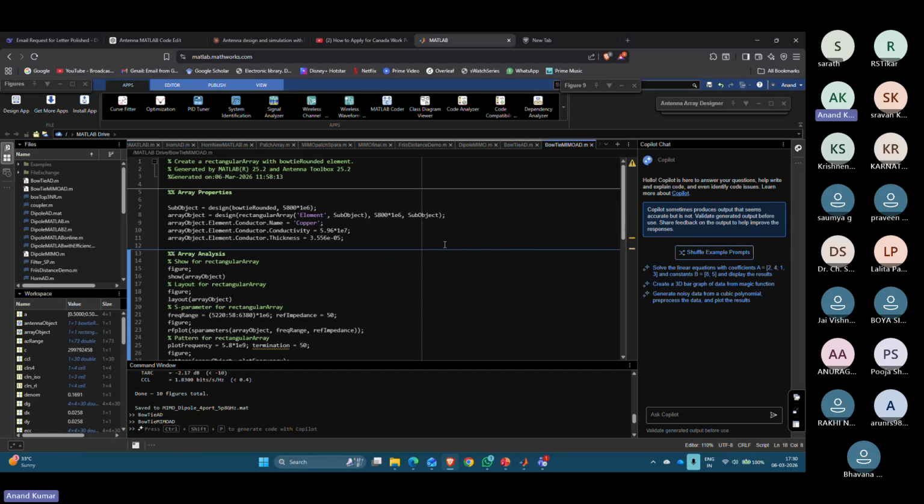It's just the one problem that I see with MATLAB right now is that it's really slow with dielectrics, because it has some problem with its meshes. I guess they'll solve it soon, and then it's pretty easy to do a lot of things. And I did not show you, but you can use conformal in the MIMO design to place the elements also at different locations. So I guess that would be another lecture in itself.